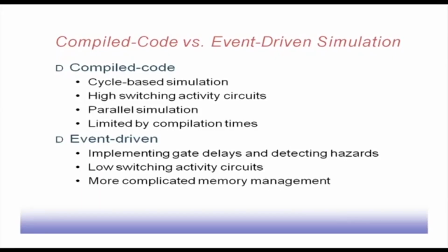On the other hand, if you take event driven simulation, the advantage is that it implements gate delay, and thus it can help in detecting hazards. Compiled code simulation is cycle based, so every time something changes it will just show that information, but whether any hazard is occurring, there is no delay. This compiled code version was basically a zero delay version, so we could not get the hazards into the picture, whereas in event driven simulation, since every transition is taken as an event,